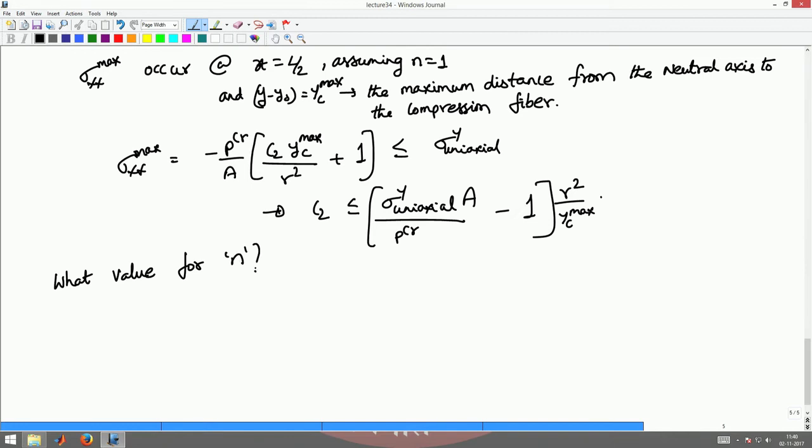This depends upon the mode of deformation that is possible for the structure. If I have a simply supported column with an axial force P applied, at midspan it can show any deflection that it wants to have, and it can deform into a part of a sinusoidal curve.